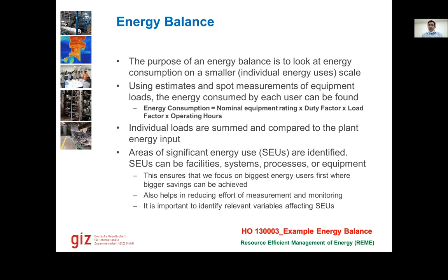Another way is to put up a power data logger there, which logs data for 1 day or 2 days, and then we might have more data. So there are different means of measuring this. And then we sum up all the individual loads, and then we can compare it with the plant energy inputs.